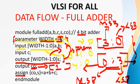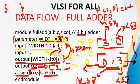And coming to this assign. For example, I have written this operator, this flower bracket indicates the concatenation operator. So basically I'm adding all this. I'm not writing any formula. For example, I'm not writing A XOR B XOR C as sum, and for carry, AB plus BC plus CA. We don't write all this. We just use the simple expression, that is concatenation of C out, comma, S is equal to A plus B plus C. So which indicates what?